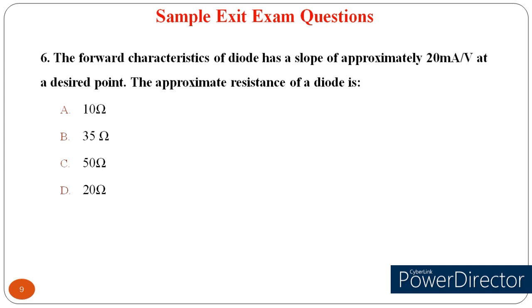There are different types of diode models. Circuits may contain one or more non-linear elements like a diode. To analyze such circuits we use diode models, for instance the ideal diode model, constant voltage drop model, and piecewise linear model.